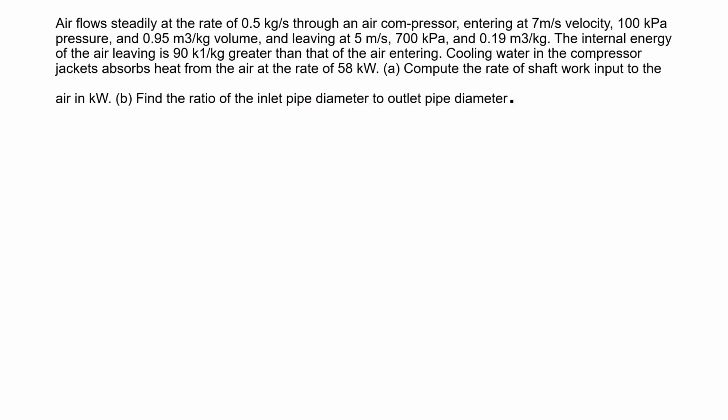So now we will do a problem on a steady flow energy device. The problem is like this. Air flows steadily at a rate of 0.5 kilogram per second through an air compressor, entering at 7 meter per second. So this is not a turbine, this is an air compressor.